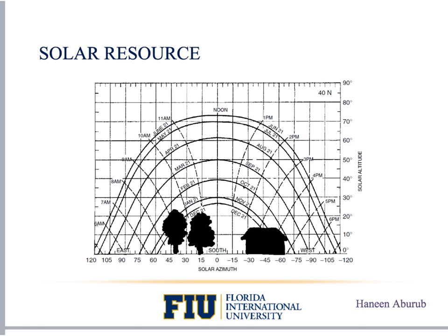Now, in addition to the sun path diagrams, predicting the shading patterns at a site is a very important consideration for photovoltaics, which are very shadow sensitive. So the figure here shows a sketch of the azimuth and the altitude angles for trees, buildings, and you can also add other obstructions if you want along the southerly horizon that can be drawn on top of the sun path diagram.